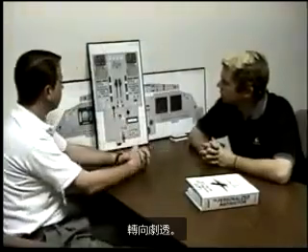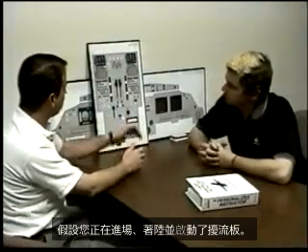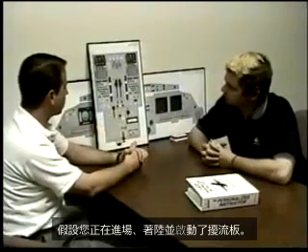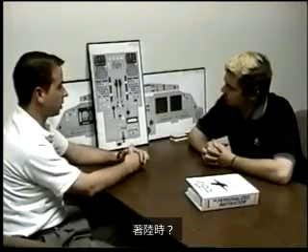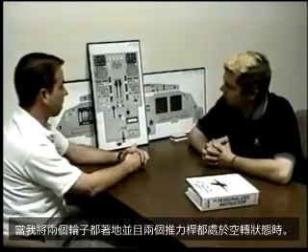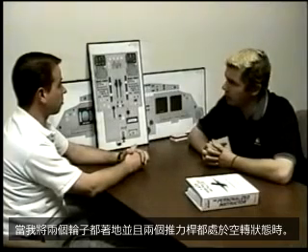Yeah. Moving to the spoilers, let's say you're on the approach, you land, and you arm the spoilers. When would you get auto spoiler deployment on landing? When I get both wheels on the ground and both thrust levers are at idle.